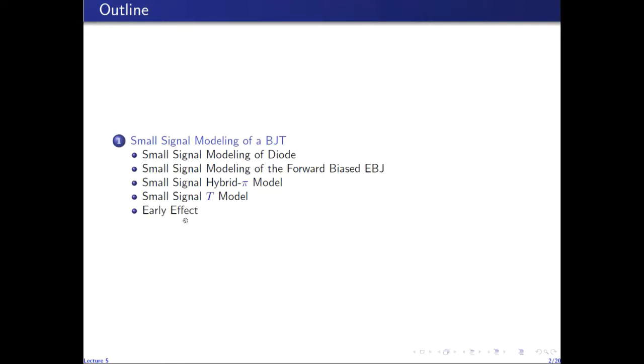Then we will study the early effect, which is a phenomenon that makes the collector current dependent on the collector-emitter voltage. And we will properly augment these two models, the hybrid pi and T model, to reflect this dependence.